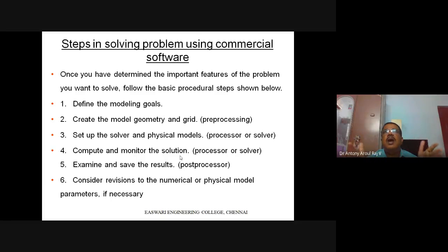All these subdomains are meshes, and they will be regular shaped. It can be a tetrahedral shape, a prism shape, or a pyramid shape, but it will be a regular shape. We will be dividing these domains into regular hexahedra, pyramids, prisms. All these shapes you can have. These are all regular shaped subdomains. And after that, we will be giving the boundary conditions.